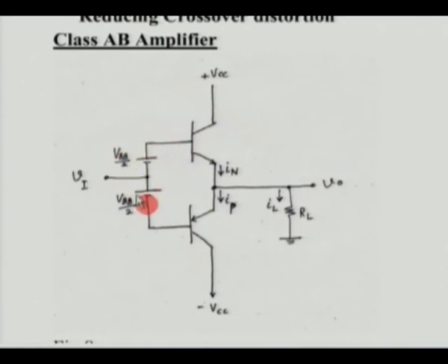So what is actually done is, you would apply a signal and listen, because you have a loudspeaker there. You would have a potentiometer arrangement which would give you some voltage. You slowly adjust the voltage, generally with a symmetrical arrangement, so that the positive of that gets applied here and the negative there, or you can even think of two separate pots. You apply voltage such that you are just at the threshold, where the distortion just disappears.